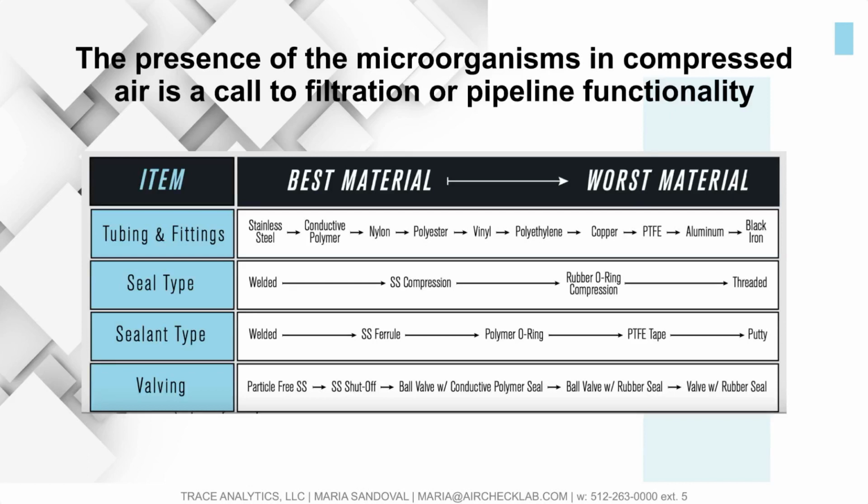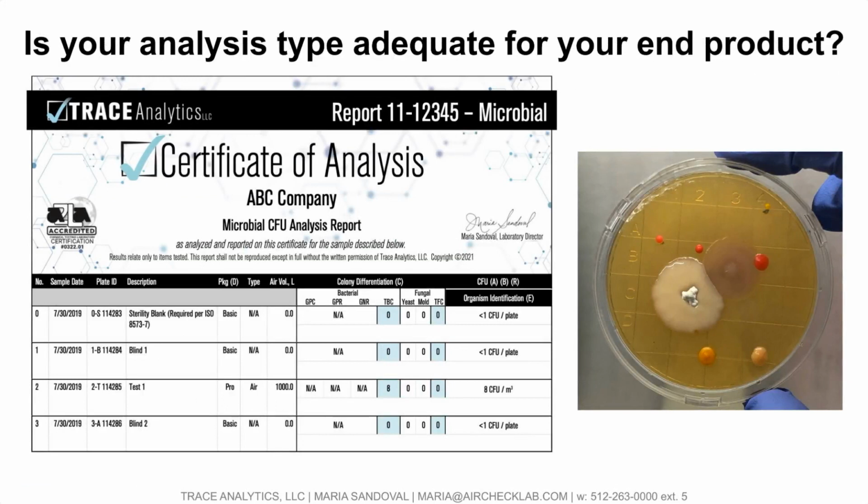You want to be using particle free stainless steel as well. So you want to be mindful of what it looks like to be using the best materials with the most efficient filters to get a very clear understanding of the functionality of your compressed air system when it comes to microorganisms.